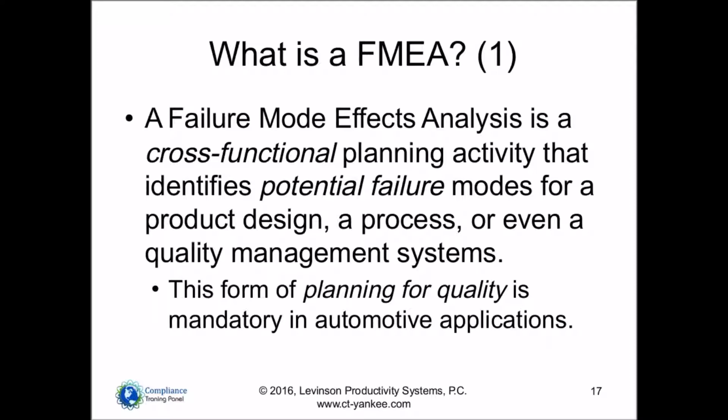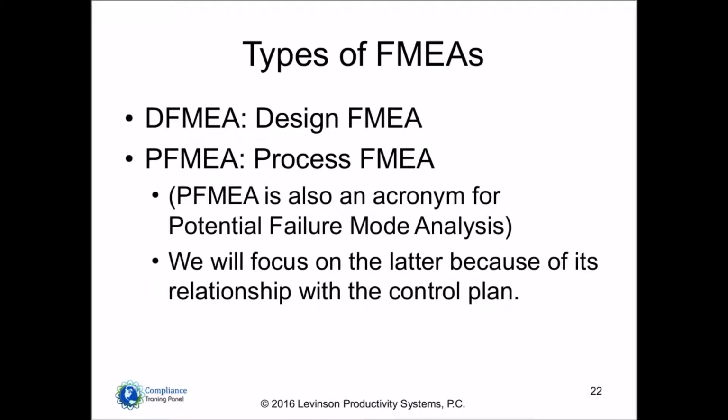It's a cross-functional planning activity, and I stress cross-functional because you need to involve not just, for example, the design group, but also the manufacturing engineers who are actually going to make the product. It identifies potential failure modes for a product design, a process, or even a quality management system. Types of FMEAs: design FMEA and process FMEA.